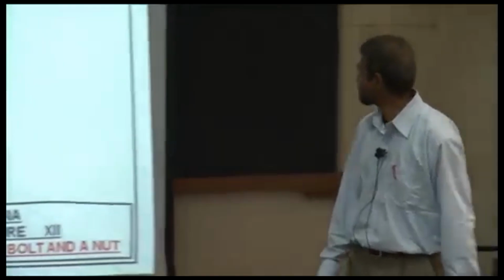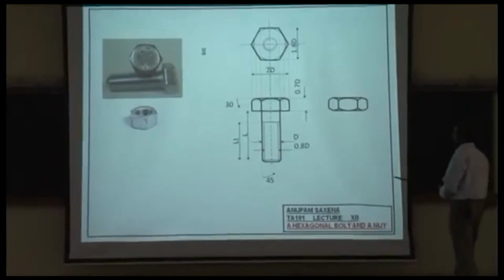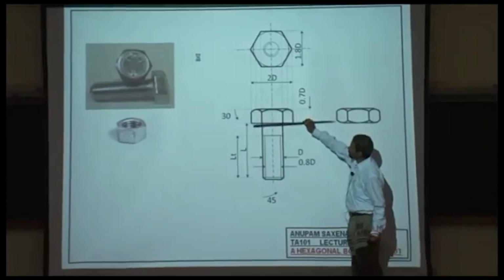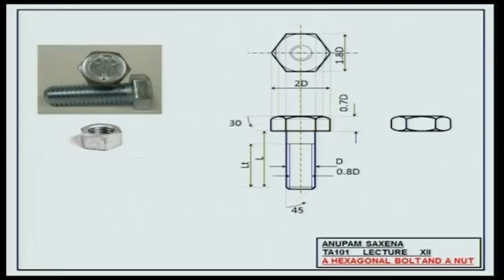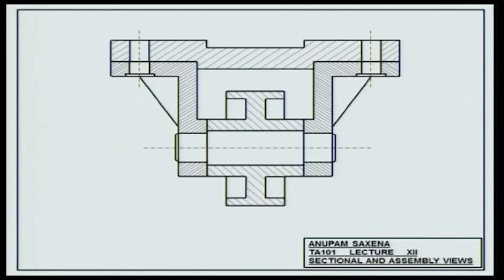But just in case, if I need to show the assembly, the full section assembly, along with the two bolts on the left and on the right. Oh, by the way, before I go there, the nut is going to be something very similar to the head of the bolt, just that this part will also appear over here. So, chamfering at both the ends of the nut. All right, so this is how the final full section assembly looks like.